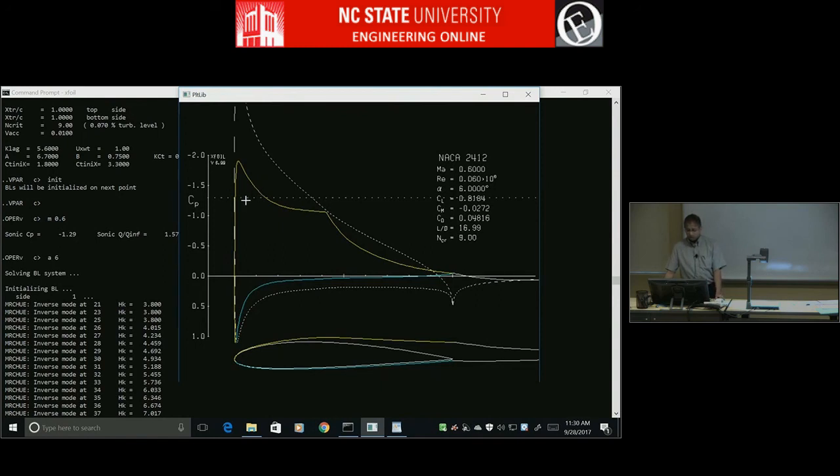It goes into beyond local Mach number becomes 1 and greater than 1. And when that happens, XFOIL is not really valid. So even though it gives a result, this is probably really wrong because the theory doesn't account for it. So XFOIL has the equations to model compressible flow, but in subcritical conditions.